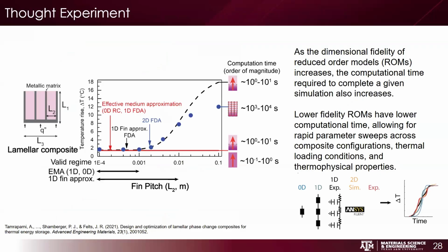Phelps's paper, so I guess this is why we're putting it in as well, is that there are regimes under which, similar to your question before, the convection is suppressed, as well as the melt front actually goes from a 2D melt front to a 1D melt front, if you get to small enough pitches.